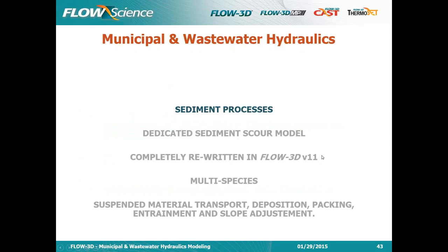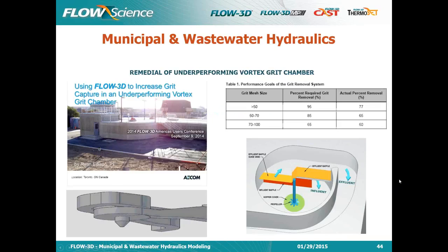So, sediment processes. Extremely interesting, very important, and we're talking about grits, particles, sand, and so we rewrote pretty much everything for Flow3D V11, which came out last summer, I think, and so we really have a nice tool now, which allows you to look at a lot of different things in a very practical, functional way. Some of the key elements are that we define multi-species, so a whole range of grain sizes if needed, and we do the transport of suspended material, using a drift flux model for that, but we also now have deposition, so when the particles reach a solid surface and stop moving, the ensuing packing, and then erosion on a packed surface, there's entrainment or re-entrainment, and then slope adjustment and bed load transport, those sorts of things. So it's become a really powerful model in Flow3D.